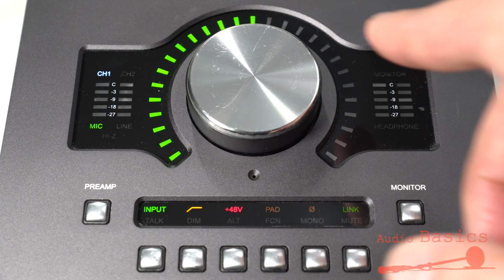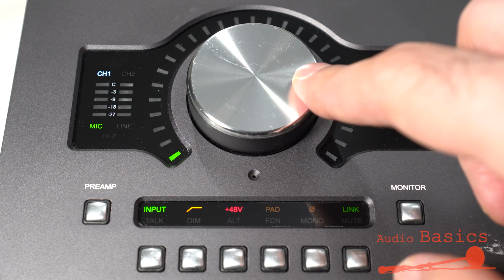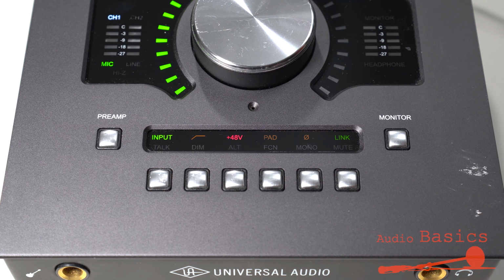Once the mic is connected to your interface, you're going to want to dial in a setting on the interface's preamp to make sure you're getting a good strong signal from the mic. Most interfaces have a physical knob for this setting, but some allow adjustment through software as well. Let's turn the preamp all the way down to start. Next, we'll want to make sure that we have the phantom power turned on if we are using a condenser microphone. Your condenser will not work unless you have this turned on.